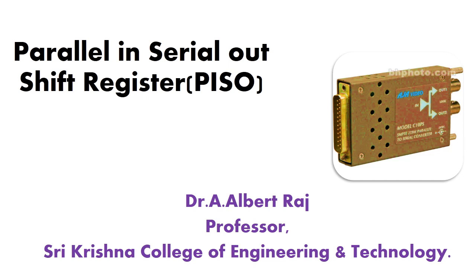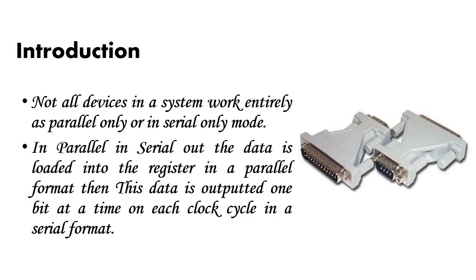In this presentation, we are going to see the parallel in serial out shift registers. Not all devices in the system work entirely as parallel only or in serial only mode. For instance, the communication inside the computer uses parallel buses that transmit parallel data from component to component. However, the communications among external devices takes place using serial data. So, parallel in serial out shift registers are required.